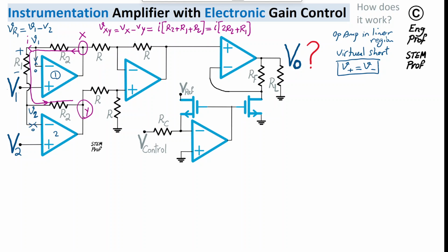One comment about the op-amps: there are many choices that we can select the op-amp from, but what is preferred is a low noise, low drift, low offset op-amp with reasonable bandwidth depending on the target application. For example, it might be a sensor, an optical sensor or whatever sensor, that we cannot draw current from.